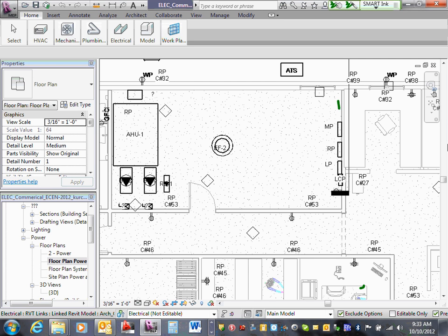And you drop them, so when you drop them all here, side by side, then you take a view of them. You take a view here, which is basically a picture of it. And that's what you guys were looking at when you were looking at the one-line diagram. You were looking at a view of this, which means if you come here, Adam, and you move this panel from this wall into here, guess what's going to happen to this view? Now, that panel will disappear from your riser.